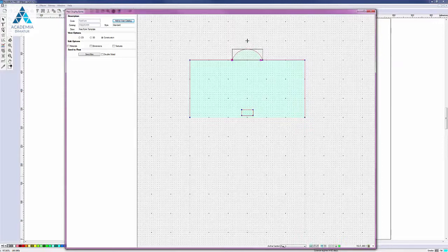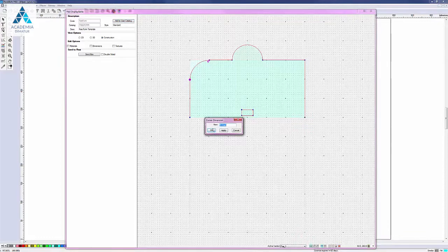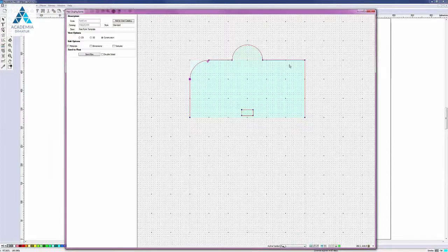We don't support having radiuses greater than the length of the baseline. However, there are ways to get around that, which I'll show you later. Okay, so in addition to that, I'll add a fillet to this corner. So right click at point, fillet corner. Now if I want an exact value I can use numeric entry, and in this case I want 50. Okay, I can repeat this here, left click, Control R.